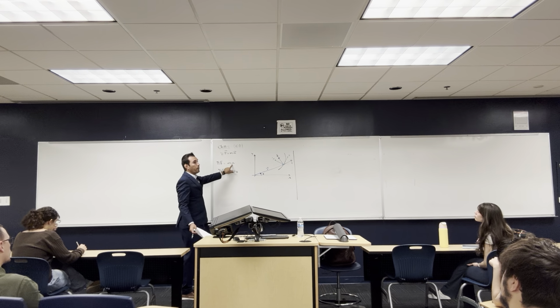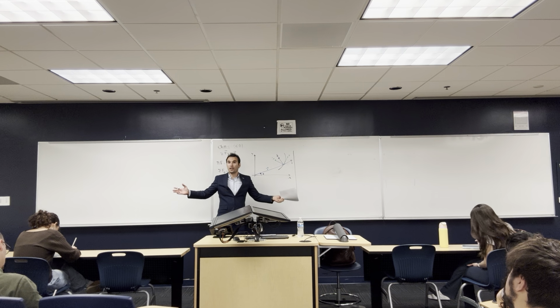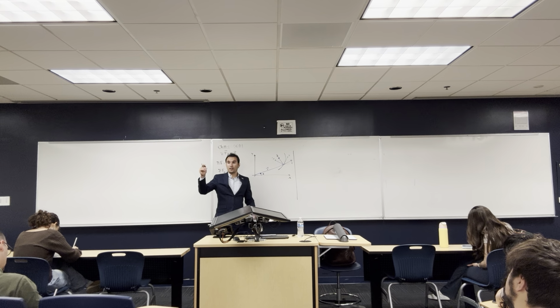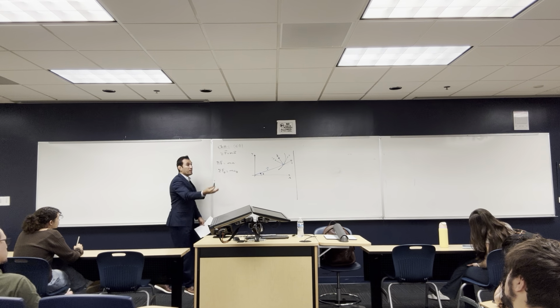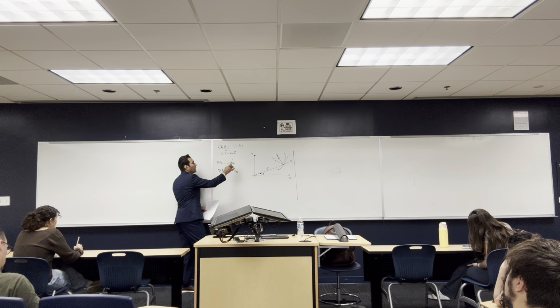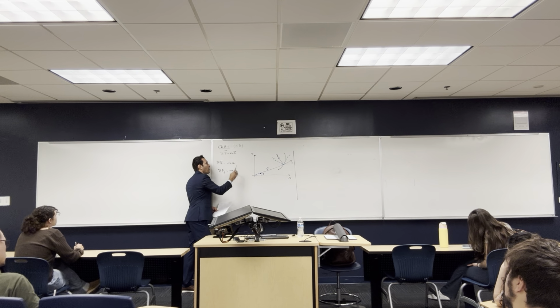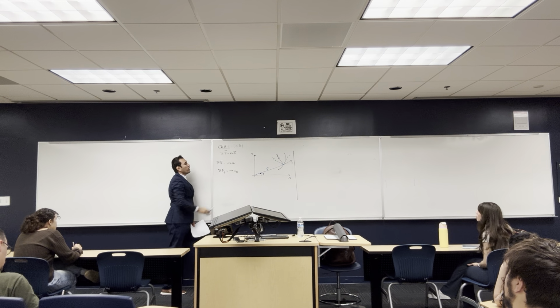Basically, in the problems, I will give you that r is equal to some function in theta. So first you have r, and then you can get r dot by differentiating with respect to time, and then r double dot. And theta dot and theta double dot are going to be given in the problem, or I can give you a way to get them. So basically, you will be able to get the accelerations a_r and a theta.